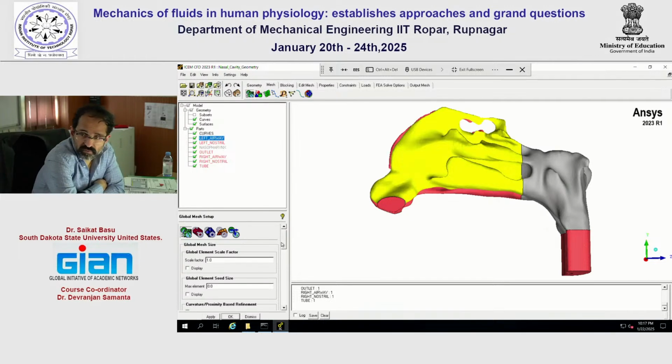If you go further downwind into the bronchial pathways, of course you need to be very careful, because you have thinner channels into the bronchial pathways, and if you are indeed tracking delivery of particles in those thinner cavities, generation 2, generation 3, generation 4, there should be enough elements in those cavities as well.